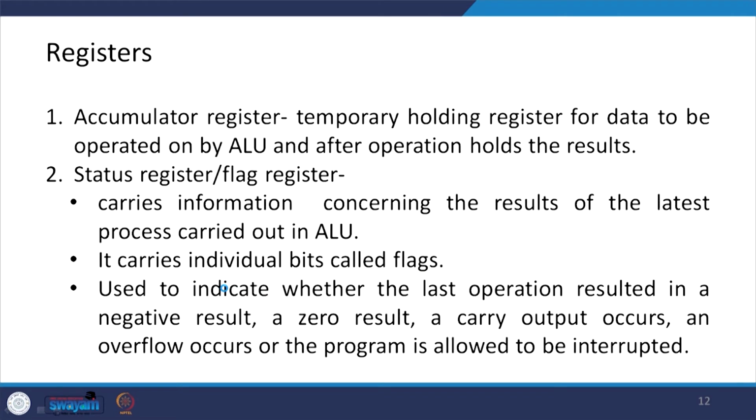Now, let us look at the different types of registers. Okay. So, we have the accumulator register, which is a temporary holding register for data to be operated on by the ALU, and after the operation holds the results. Then we have the status or flag register.